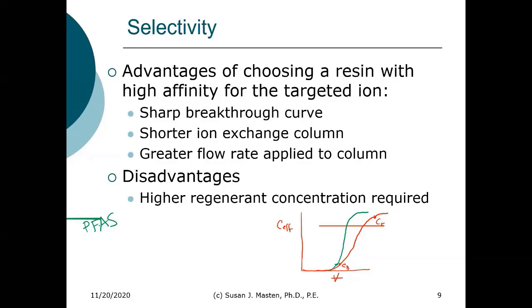the carbon-fluorine bond. So if we use an ion exchange system to remove PFAS chemicals, we now have the PFAS chemical on the resin. If we regenerate it, where is the PFAS chemical? So here's our ion exchange resin. We'll run through it in. So we load the column with the PFAS chemical. Now we have PFAS on the resin. And hopefully we have clean water.